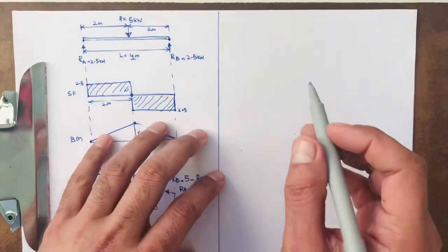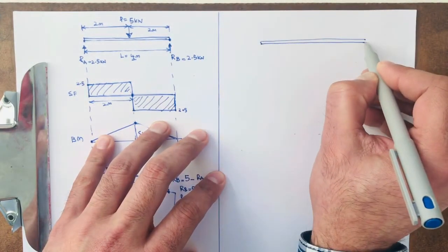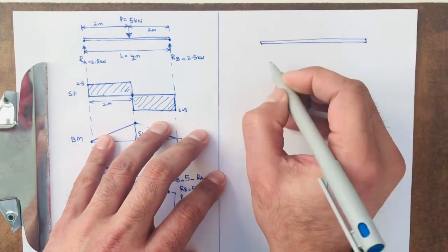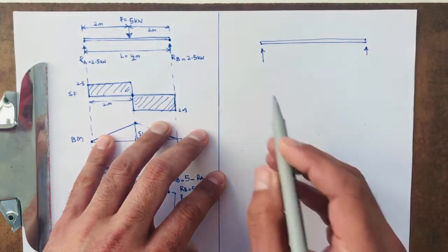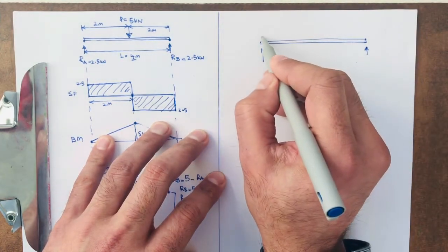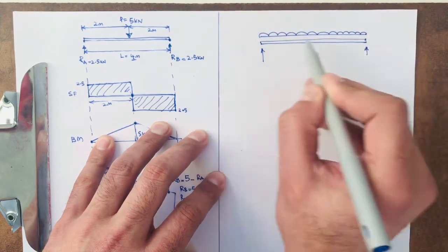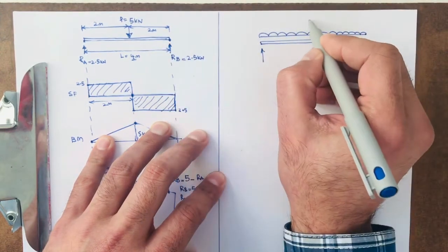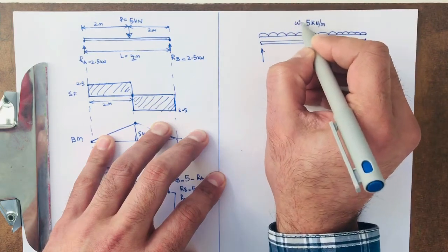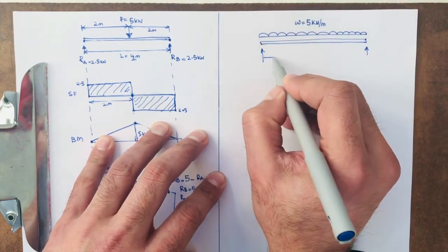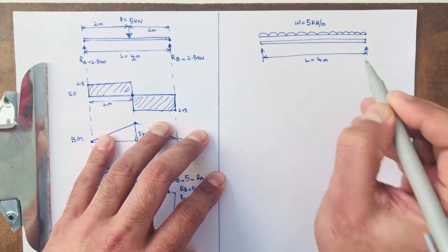So let's start with the second case, a simply supported beam. I'm going to assume exactly the same length and same loading, but a UDL. So reaction here, reaction there. It's a simply supported beam with a UDL in this scenario. I will imagine this is a UDL, uniformly distributed load. I'll use the same magnitude, 5 kilonewton, but in this case per meter, and I will call it W. The length, I'll keep the same as previous, L equal to 4 meter.